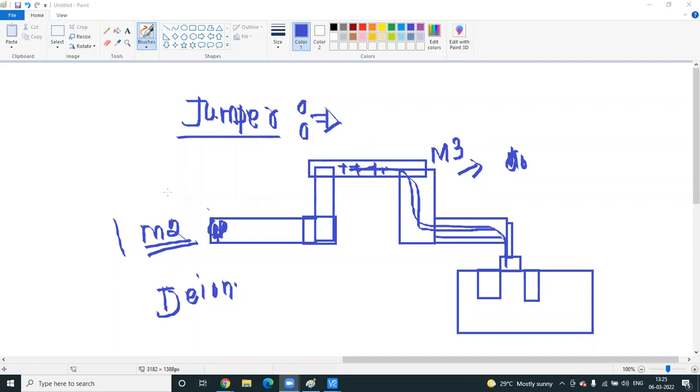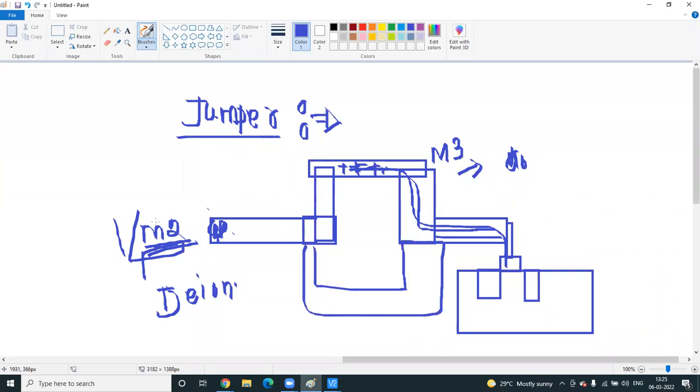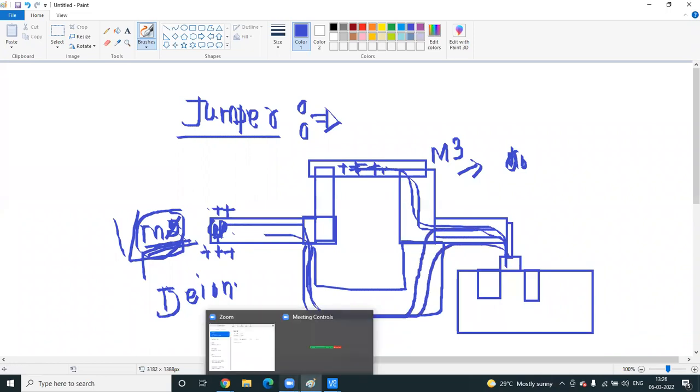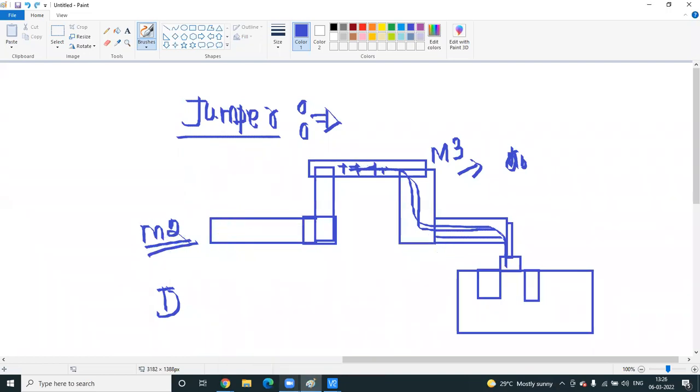Okay. So what I am trying to say, M2 is already completed. Already completed means it has no charges. So charges are only in the next higher metal. But if you do M1, this is already fabricated. Now charges are only in the higher metal, whose process is not completed. So charges are present here. Understand? So now if you calculate the antenna ratio for only this much layer, it is of no use, and it has a path also there. Understood, or anybody having doubt?